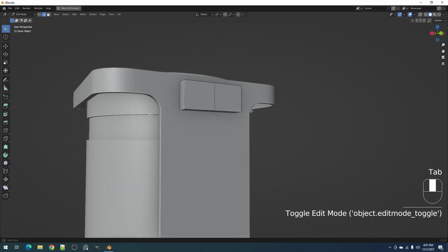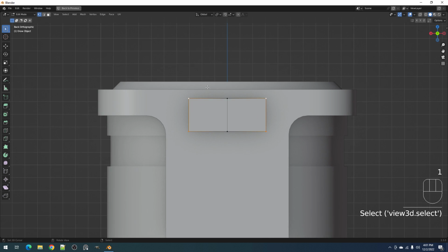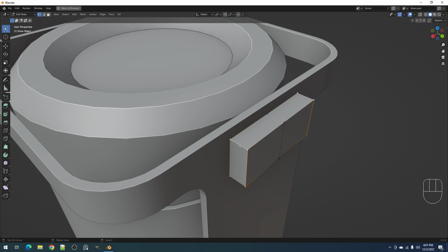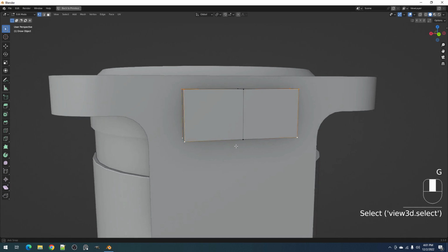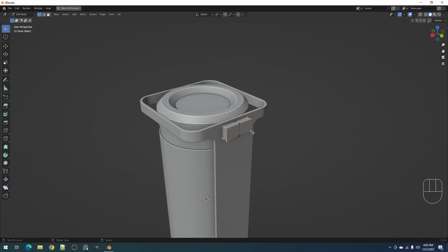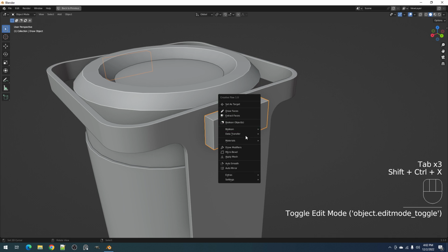So I can't design this on this side. I can design this on this profile because this is the view that we used to draw. So this thickness here is provided by the solidify modifier, so I can't edit that, but I can edit the profile in the view that we used to draw the draw object. But to affect everything, we must turn this into a real geometry.